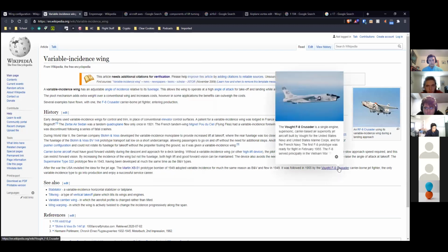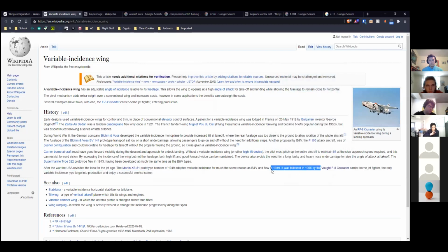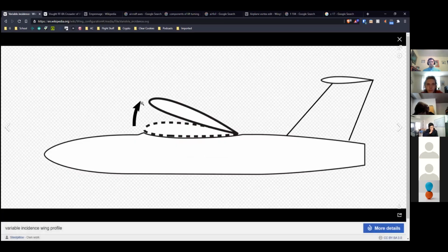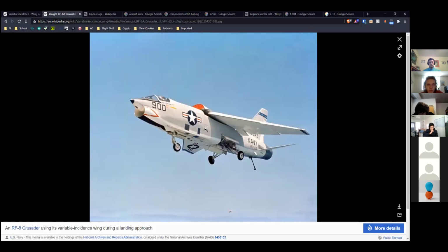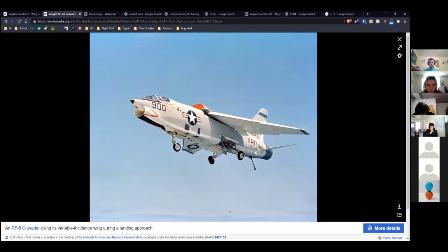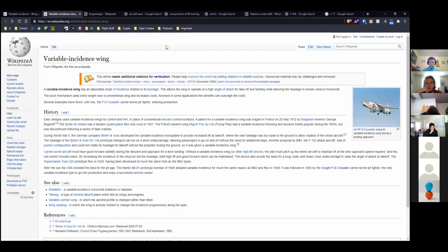I've definitely read this article before, and I think it said that the visibility was improved because you have two options if you change the incidence. You can either keep flying the fuselage the same direction and then the wing just creates more lift, or you can get the same amount of lift and then just droop the fuselage down. And so I think they got a little of both, somewhere in between. So I think they got somewhat better visibility, if I remember that right. But that was just an added benefit. The reason they built it like this was to have higher takeoff and landing lift.